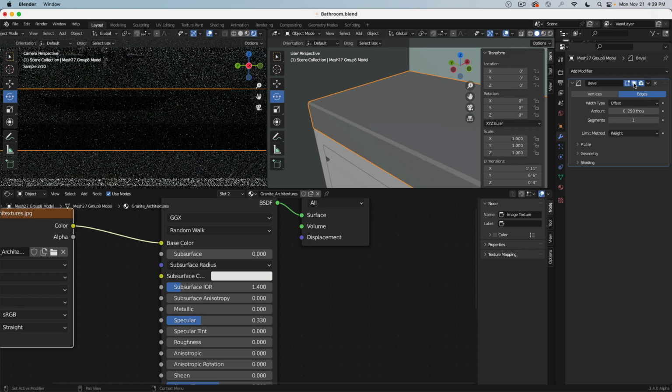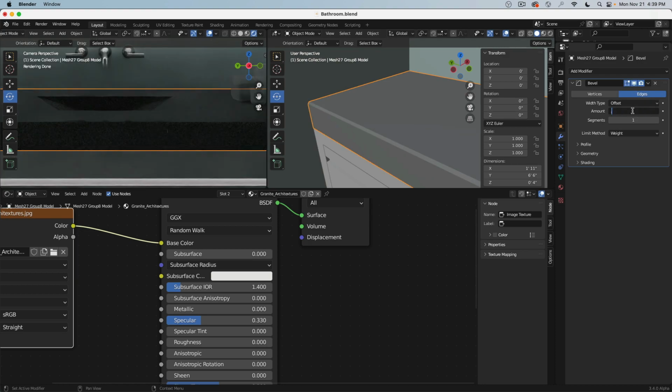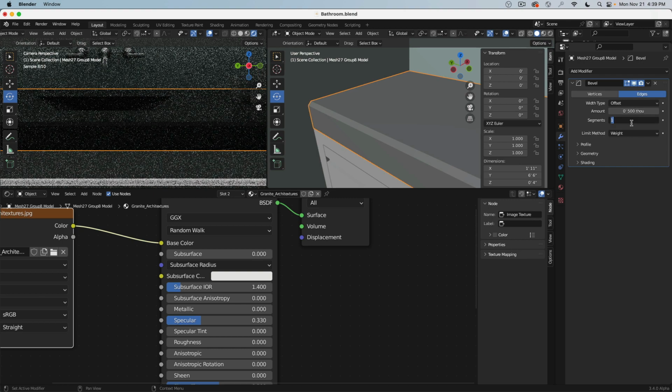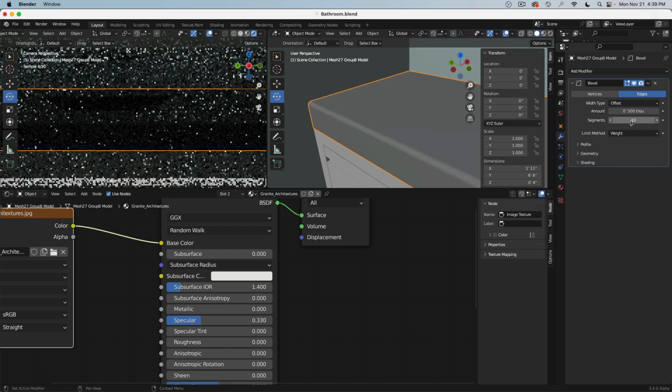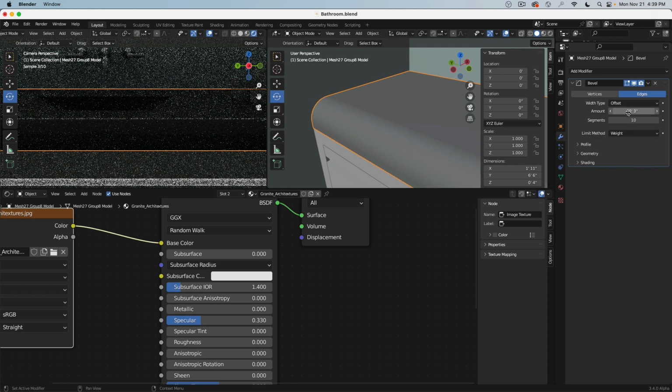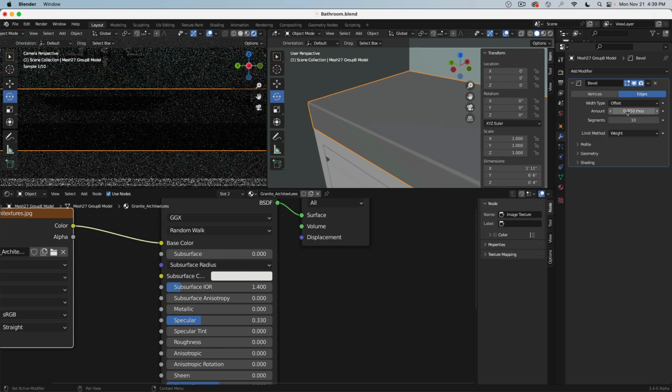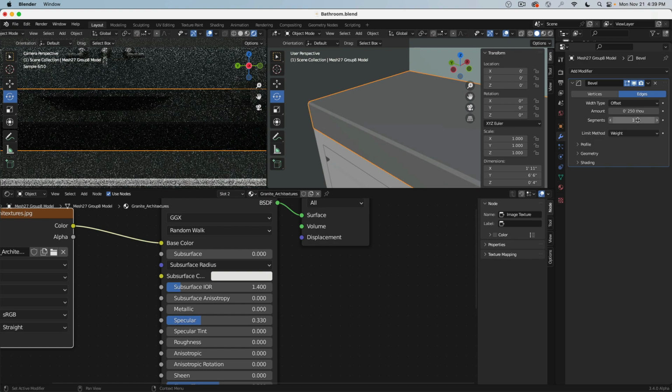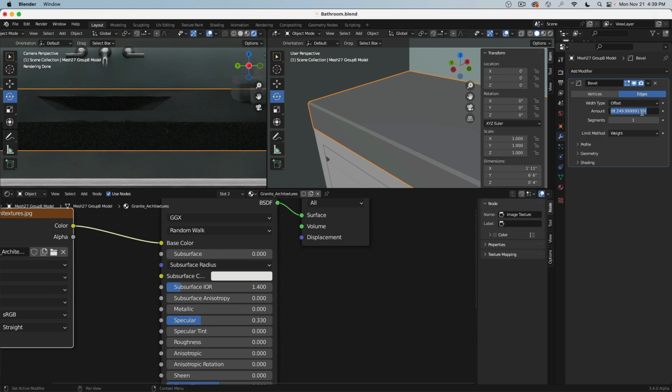And you see this is an effect that can always be overwritten. Can also make this round, so bevel turns into a chamfer. 0.25 of an inch to make this really small. Chamfer, maybe 0.125 of an inch.